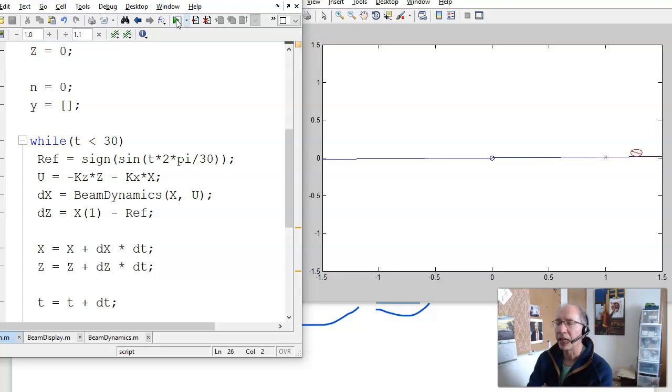I have to add extra torque to counteract the force due to gravity. And there it overshot because the extra mass caused the beam to go down, ball to go too far. The integrator eventually figures out what you have to do, and it brings the ball back to your set point. That's what a servo compensator does.